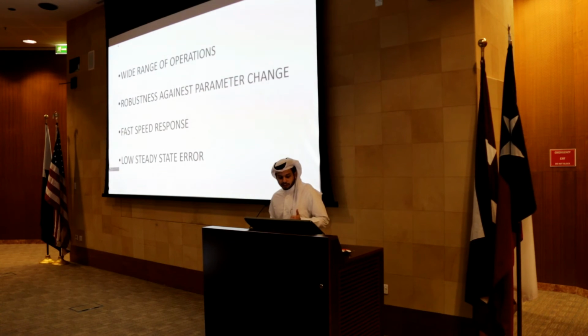1. Wide range of operation, such that the motor can drive the application at different speeds with similar speed responses. 2. Robustness against parameter changes, to be stable and accurate across its operation. 3. Fast speed responses. The motor has to adapt quickly to input speed changes. 4. And finally, low steady state error. Some applications are sensitive to the error in the driving motor, so the steady state error must be low.